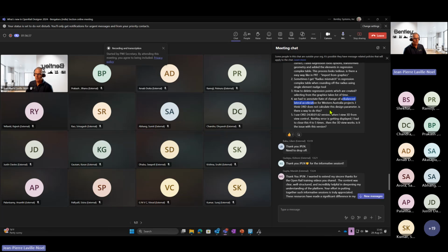For cant, there is a way to do that if it's on profile, on plan. Not easy. Really not easy, except through creating points, geometry points, by export import maybe if you don't want to do it manually, and adding item type to the points and calculating the information. So nothing really easy at the moment, but we'll check that. Let me take a note. Unbalance. It's a requirement.